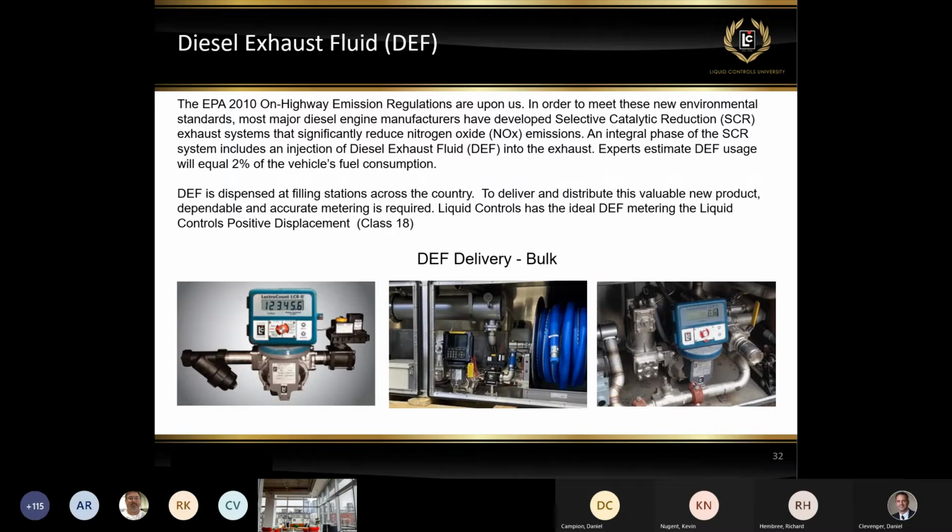What we've recommended in the dedicated tank system is using an optical sensor on the discharge side of the tank. The position is critical because it's based upon flow rate. But what it does is it will shut the valve down once the tank starts to come to empty position. Therefore, if you don't put any air into the system, you won't have to try to bleed it out.